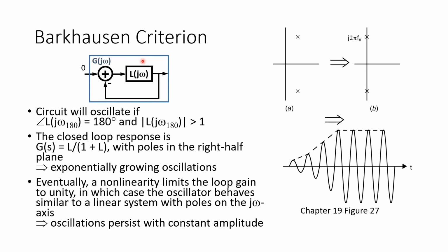You can think of the operation as if there were some input to the oscillator circuit, which is nominally 0, but where any tiny noise event, even a single electron worth of noise, can initiate some oscillations in the circuit. Now, the closed loop response of this feedback loop we'll call G. G can be the closed loop linear response when oscillations are just starting, so there are relatively small signals only present in the loop.